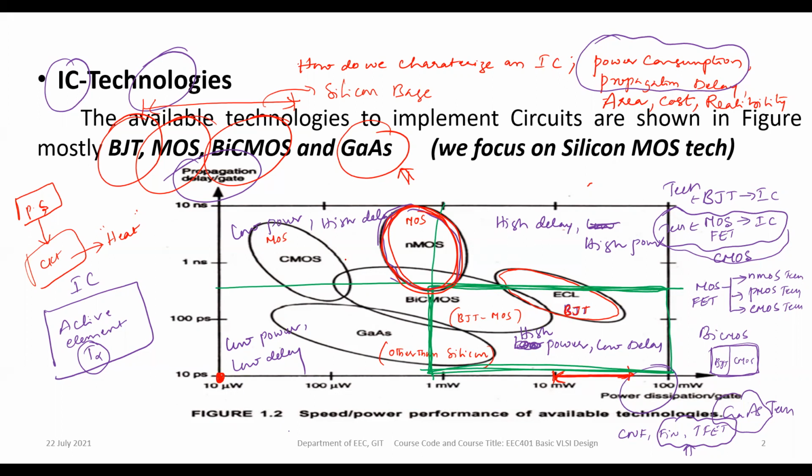Later, people realized the ICs with the help of CMOS devices. Therefore, the problem was that the power consumption of the circuit is very high, right? Now the power consumption is changed to a low power consumed device if you're using the CMOS technology. Therefore CMOS is very popular because it consumes less power compared to the other technologies, bipolar junction transistor technology or NMOS technology. So why does CMOS offer less power consumption?